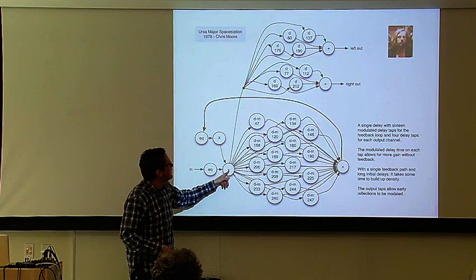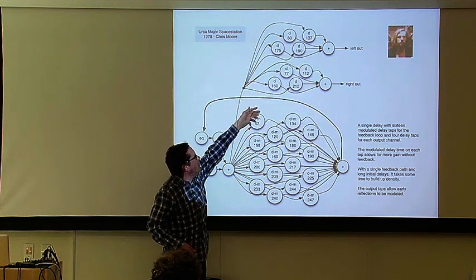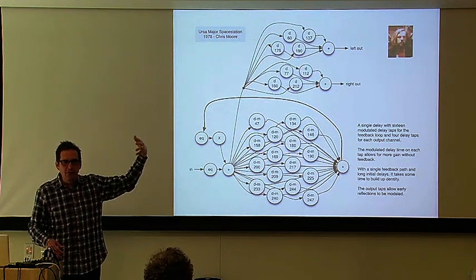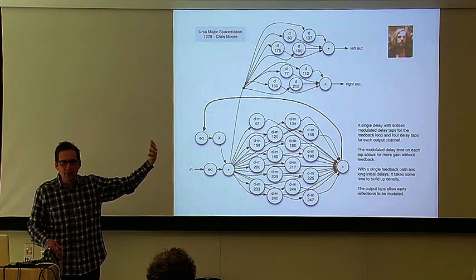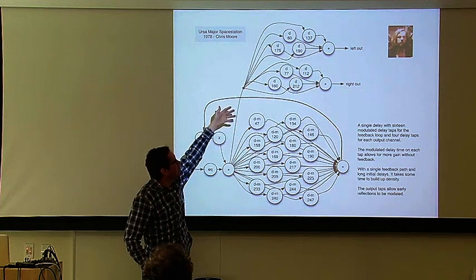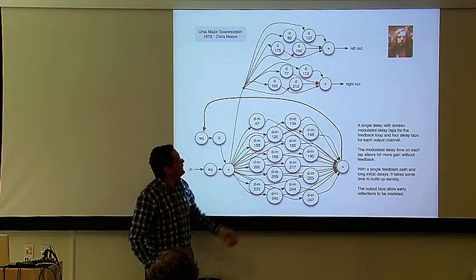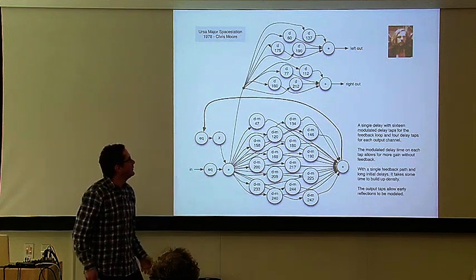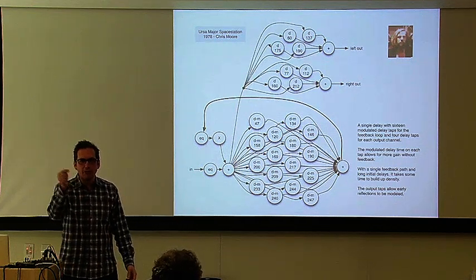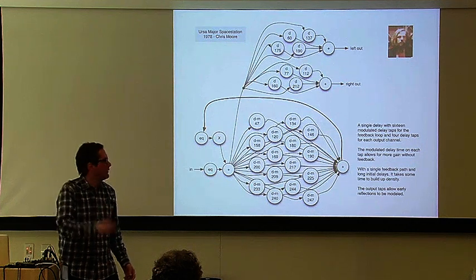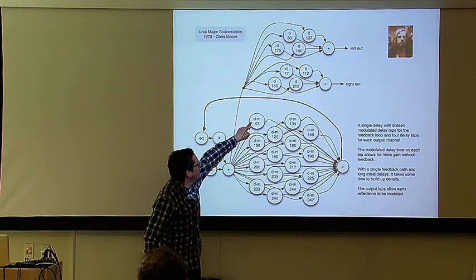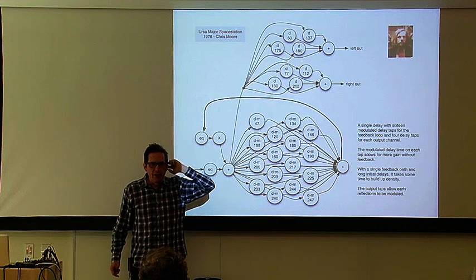And then finally, on his output, he did the same thing Andy Moore did, and he added an early reflection network. Now, it's on the output. This is convenient from an engineering point of view, but you can put this on the input or the output. It will do the same thing. These are a set of reflections that allow you to model different sizes of rooms, different kinds of rooms. And if you look at an Ursa Major Space Station, it has push buttons to trigger different sets of early reflections.